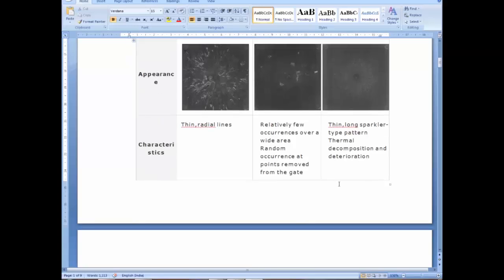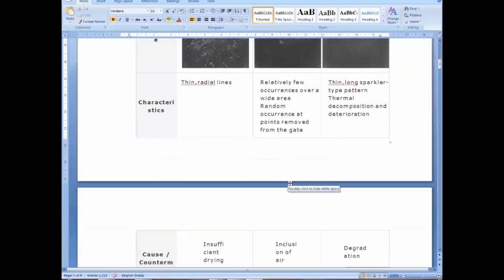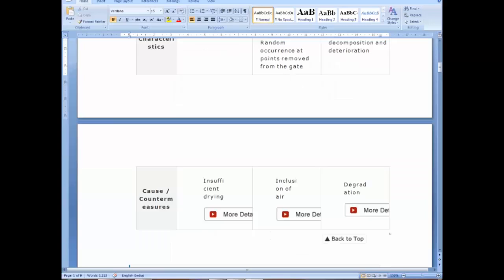So we have to always make sure that no gas is trapped inside the mold. We have to do proper venting, always giving air vents inside the mold. Small fine lines are sufficient to let all the air out from inside the mold.